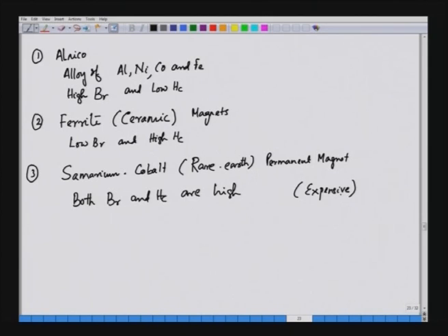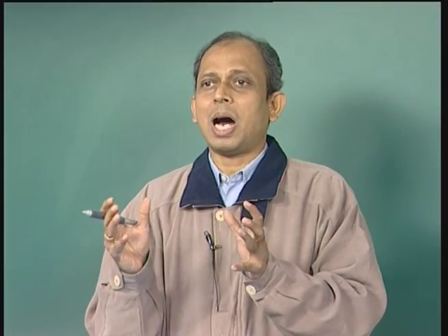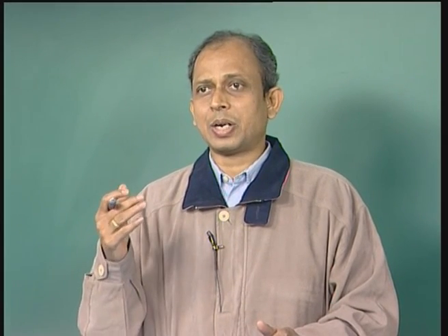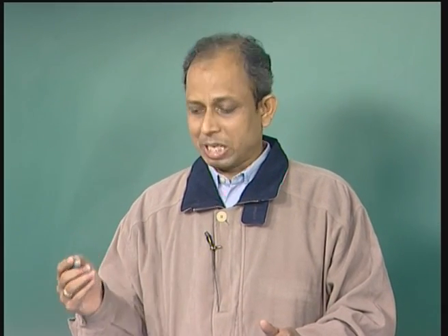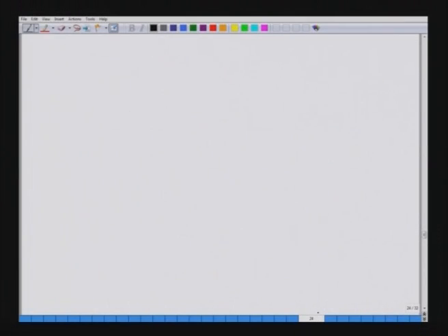They are used in those machines where we want a very compact volume, because they have large energy density. We will be discussing the energy density also. Now, energy density is a product of B and H. So, if we have a material with this BH curve, B is on the y axis and H is on the x axis, and this is the second quadrant BH curve.